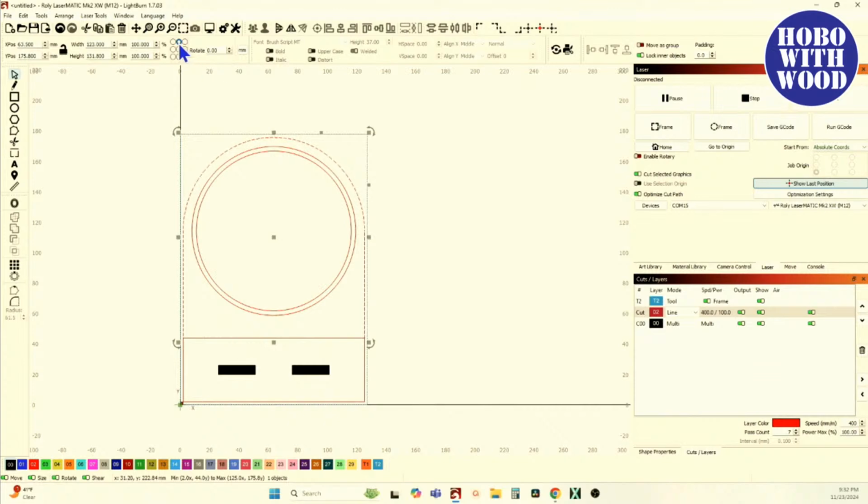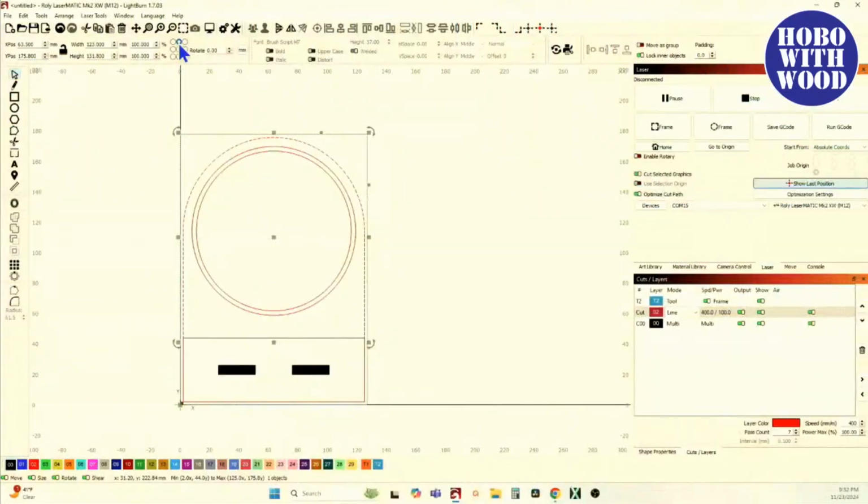I've got my anchor point there. And actually, because I screwed this up, if I change the height of this, it's going to adversely affect the arcs, the radiuses I just put on there. In fact, I'll show you what happens and why. In LightBurn, priority is everything, or even when you're designing. But whenever you want to do your Boolean tools, you want to select this one versus this one first to get the results you want. Priority matters. And so I'll show you right now.